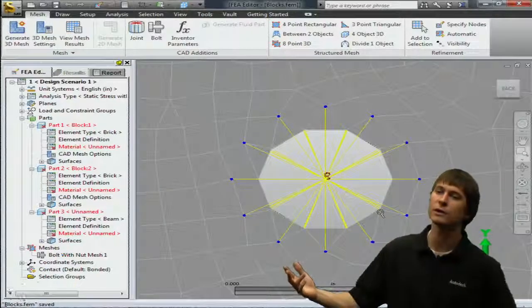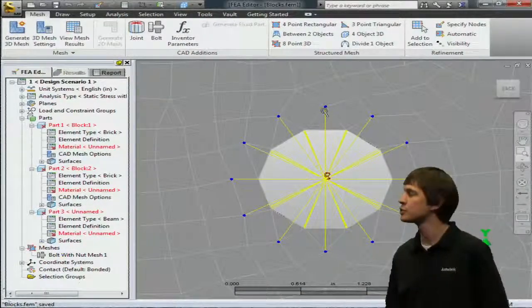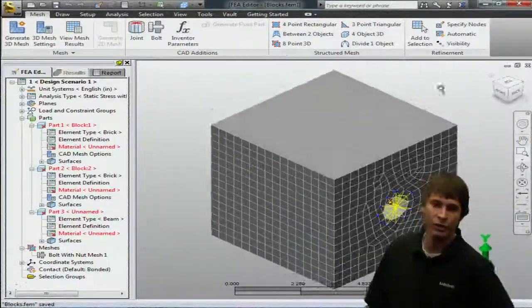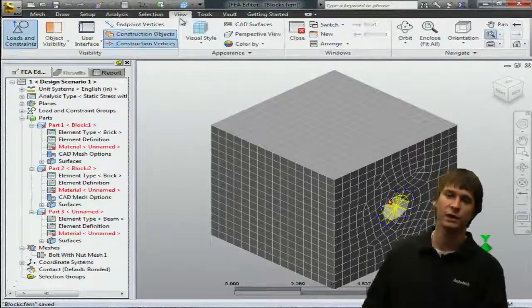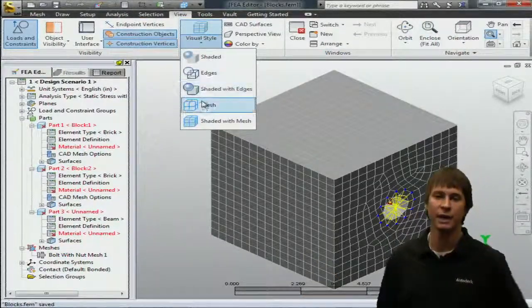So what's this doing for us? Again, it gets rid of all of those 3D bolts that you've been creating with all the threading that you can't get to mesh successfully, or even if you do, take a long time to analyze.